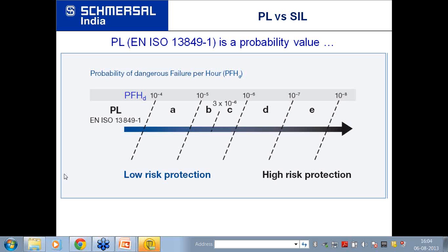Mr. L. Srinivas has asked which type of safety relay we could prefer, which is built with intelligence. To tell you, sir, all safety relays available in the market have intelligence inbuilt. So any make, any product, any safety relay you can use. Just ensure that it is performance level E or at least performance level D certified. But all safety relays are supposed to have intelligence inbuilt into the safety system.